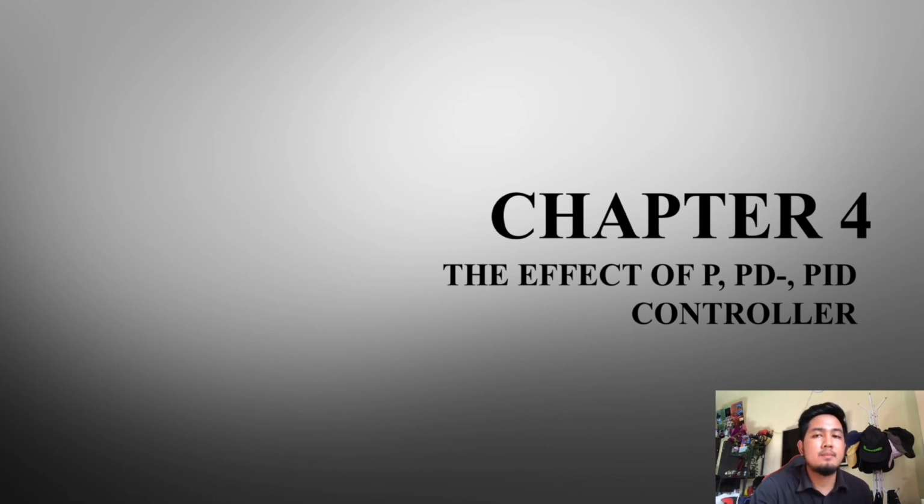I'm going to present my part, which is chapter 4, the effect of P, PD, and PID controller. The effectiveness of the system and its ability to maintain and manage a desired water level in the tank were investigated using MATLAB simulation. It is simple to simulate the system and see the outcome for various values of KP, KI, and KD controller parameters since the PID controller is integrated into MATLAB. By adjusting the parameters until the design criteria are satisfied, an ideal or acceptable result may be produced.